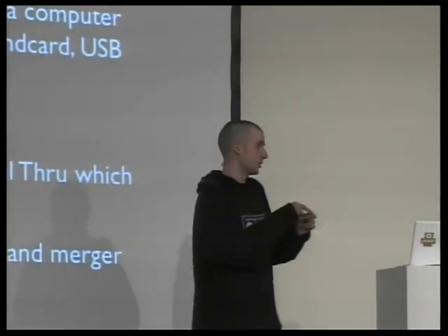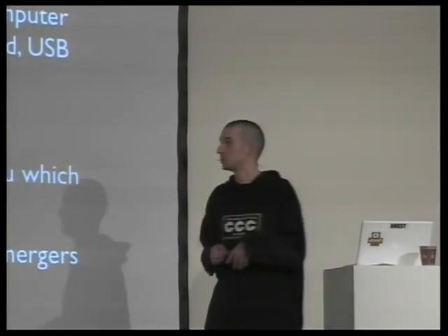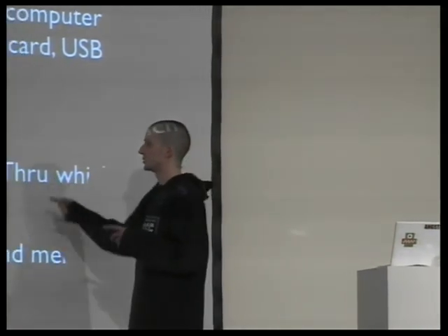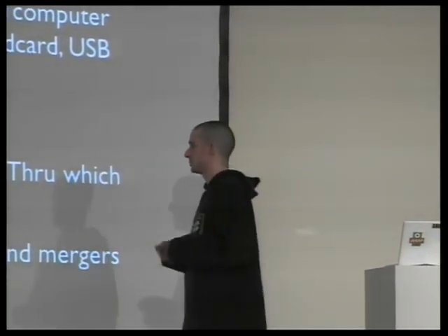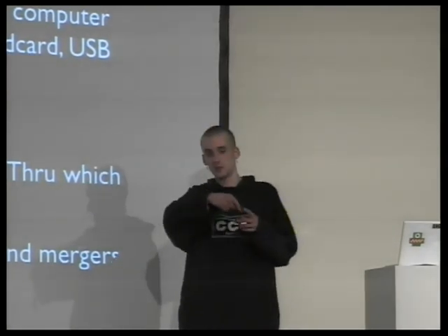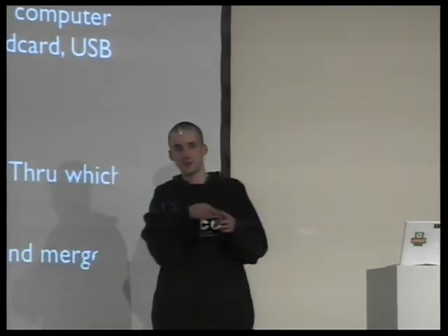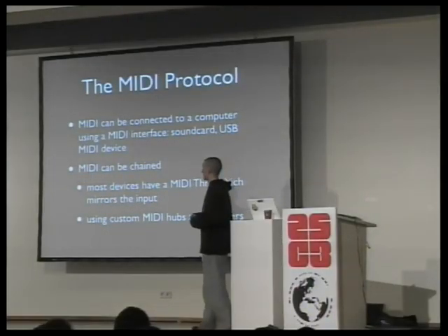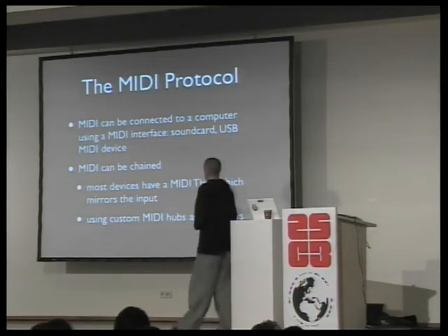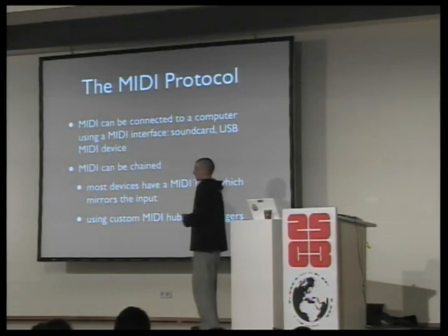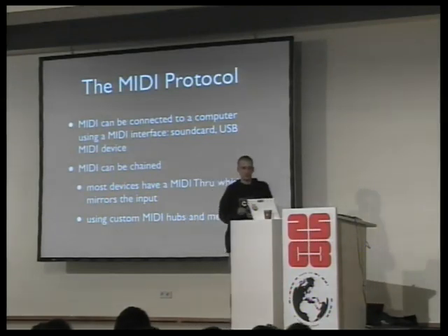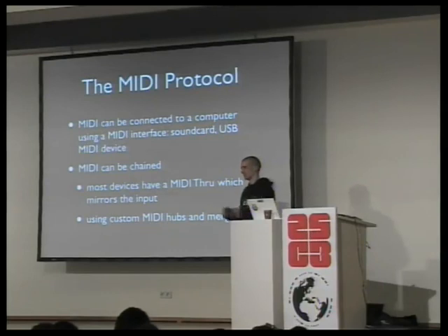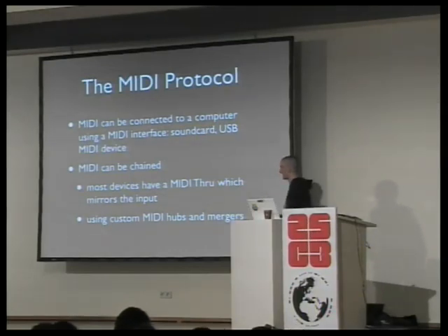The MIDI bus is a serial bus, and on most devices you have one input port, one output port, and a through port, and this one just electrically mirrors the input port. So you can chain multiple synthesizers and have them all respond to the same data that's sent in. And if you want to do more complicated stuff, which is almost always, you have to use custom MIDI hubs and MIDI mergers. If you want to synchronize some device of a friend and you want to send clock to it, then the nightmare starts, and it's like drawing network topologies when you're setting up a network at a LAN party.